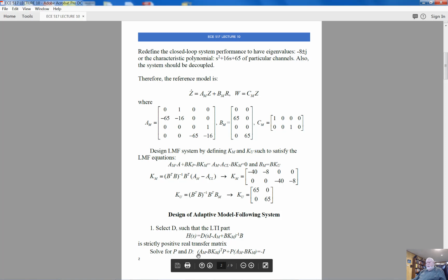And we have to use for this purpose the Lyapunov equation. In the Lyapunov equation, this is A closed loop transposed, this is A closed loop transposed. This is supposed to be any arbitrary positive definite matrix taken with a minus sign. And I always use the unity matrix. And matrix P is the solution of the Lyapunov equation.